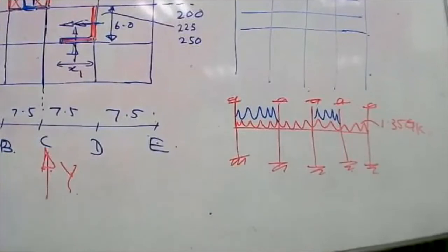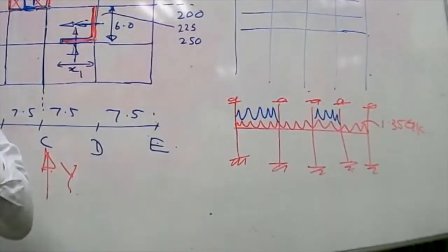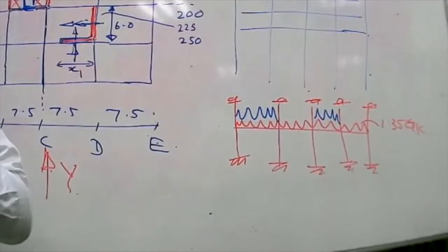The UK National Annex specifies the alternative spans loaded maximum. Sri Lanka's national annex has also gone along with the UK method. So we can use all spans loaded fully, or alternate spans loaded with maximum and the others not loaded.